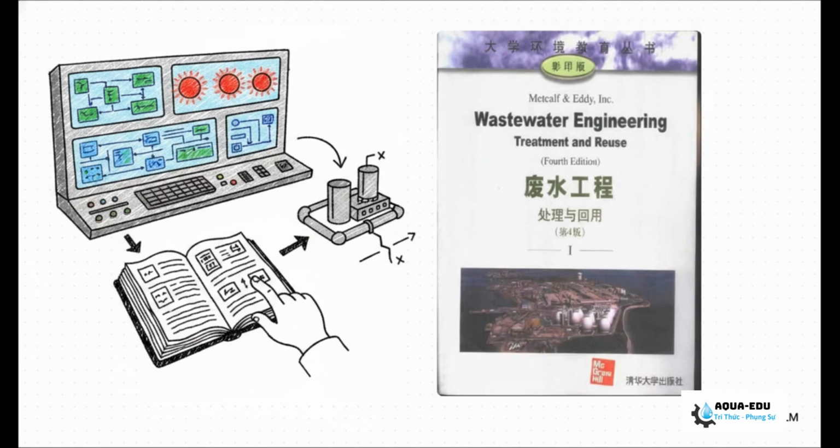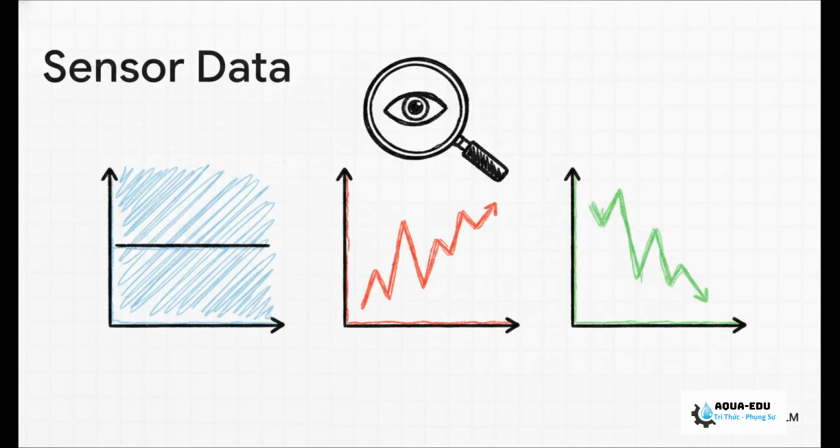And the second you spot them, it is time to crack open those manual reference guides and gear up for immediate manual intervention. Digging a little deeper into the data, you really need to pay close attention if your sensor values just flatline. If those numbers stand completely still for a long time, especially when there are obvious physical process changes happening, that sensor is dead. Likewise, keep an eye out for readings that suddenly jump way beyond physical limits to show overrange, which means greater than 20 milliamps, or underrange, where they drop below 4 milliamps on your current loop.